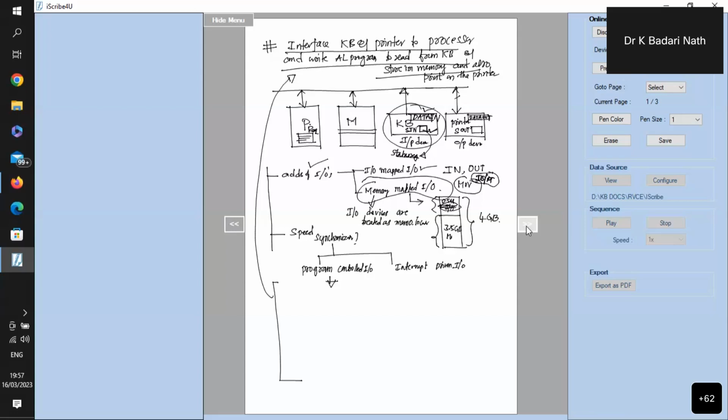So now what we'll do is, I want to test a particular bit in the status register. We will assume bit number 3 is associated with the SIN flag. So whenever I read the status register, I'm interested to look at what? The third bit, which represents the status in. So if the bit is set, the keyboard has got a character.